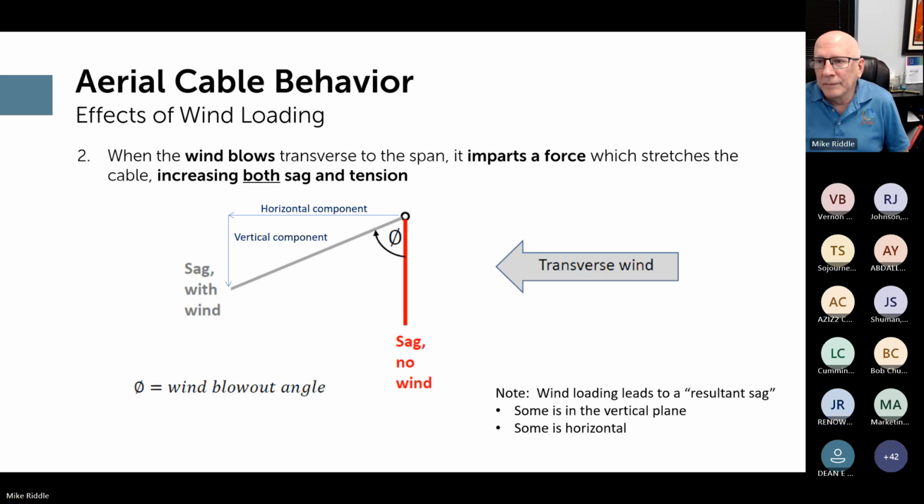So my preference is always to have the conductor installed with some sort of survey instrument or sag boards or some of the other installation techniques that actually measure the sag quite precisely, rather than the tension. Yeah, I agree. But that's personal experience and preference.